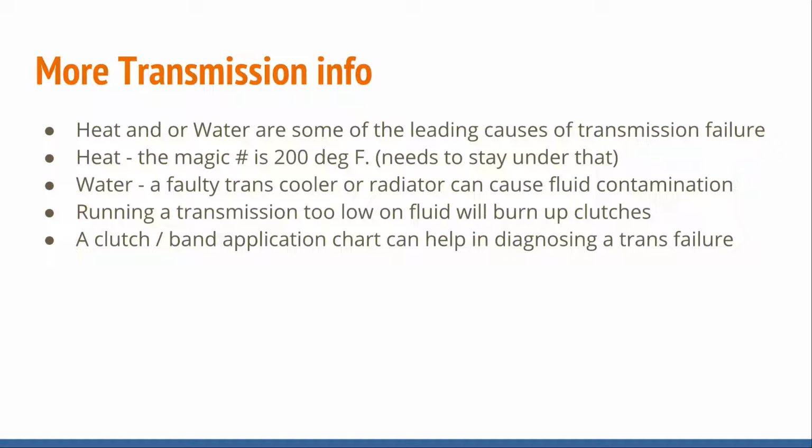Another thing is, whenever you get a transmission issue in, we always like to do the following. Say a customer brings a transmission in and he says the transmission feels like it only has first and third gear. Well, I always like to grab the scanner and drive it and see if the transmission is doing what it's being told or if it is doing its own thing. So I like to watch what's called gear command on the scanner. You go drive the vehicle, I see first gear is commanded, now I see second gear is commanded.